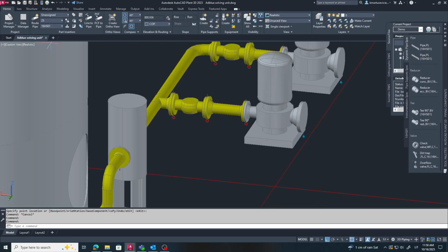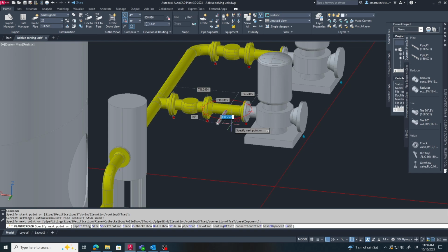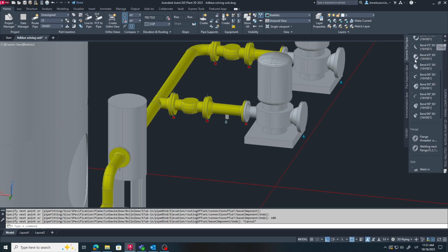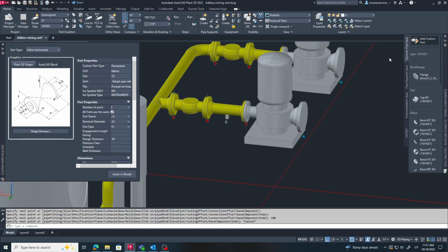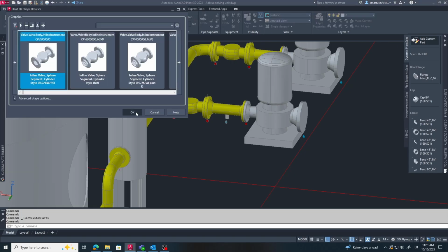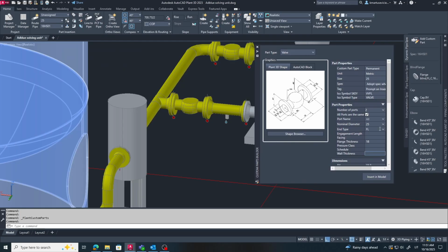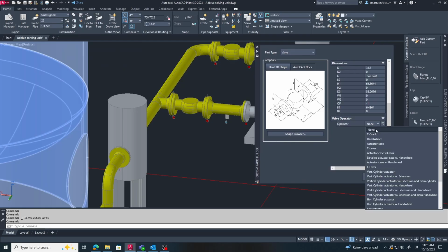This filter will remove mechanical impurities from the AdBlue solution, so the quality stays consistent and stable. Later, we will add pressure indicators on both sides of the filter to monitor when the basket inside needs cleaning. This small logic of redundancy, filtration, and monitoring is part of reliable plant design, and you will see this many times in different industrial units.